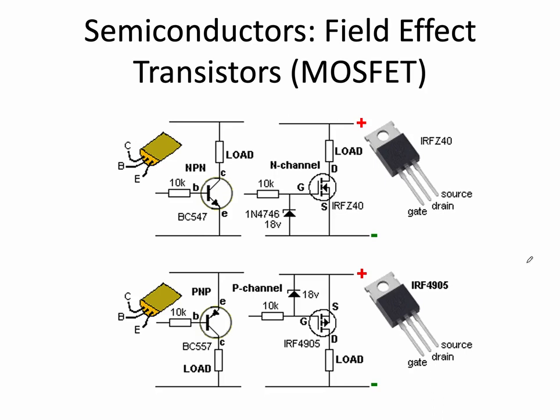There's two types of MOSFETs, just like there's two types of transistors. The N-channel is a lot like an NPN transistor, where you put a positive voltage at the gate to turn it on. And there's a P-channel, where the parts below it here are P. Sorry, if you remember, these are both N down here. P-channel has P on both sides of this.